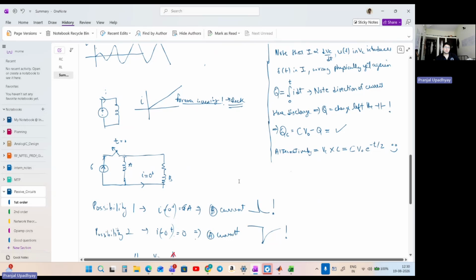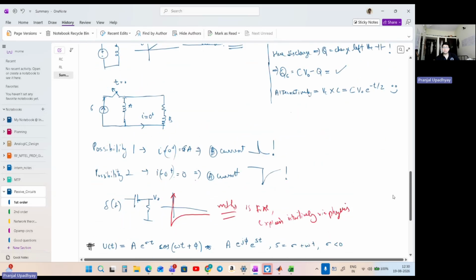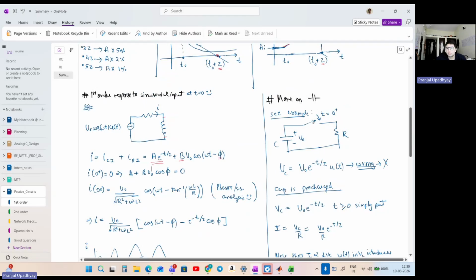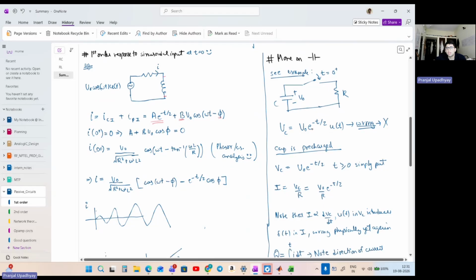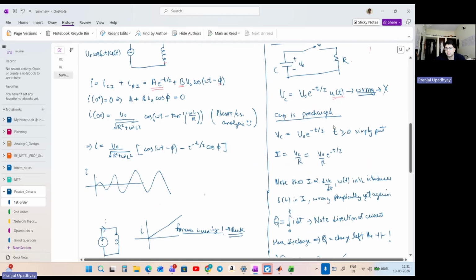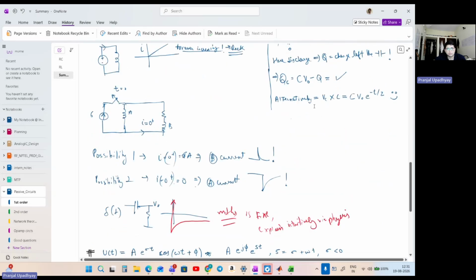Now, as I was mentioning before, I have now written more about capacitors. So here, when I close this resistor, I'll say that the voltage across this capacitor will decay exponentially. So is writing it as exponential times u(t) correct? It's obviously wrong, because u(t) basically means that this capacitor voltage is decaying like this. But you must understand that when this capacitor is pre-charged, its voltage is at some finite value even at negative time, and then it will decay, right? So that's why this u(t) must be used very carefully. That is the idea that I wanted to convey.